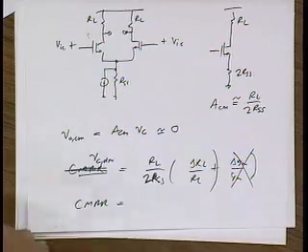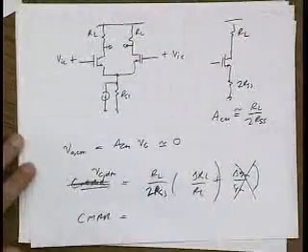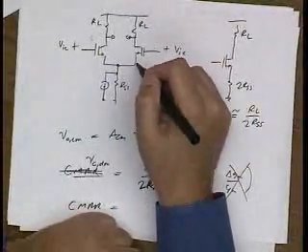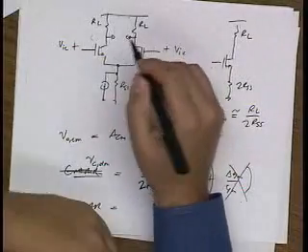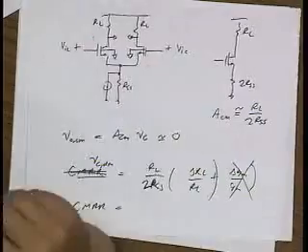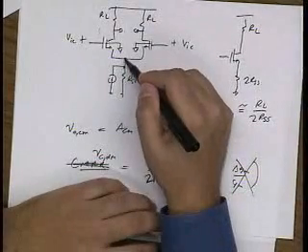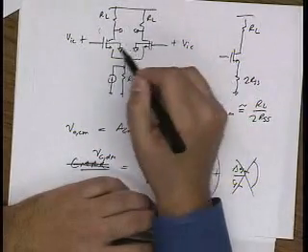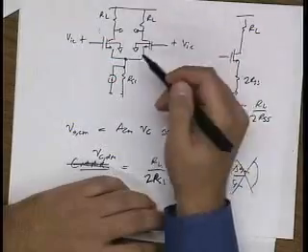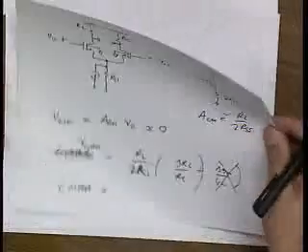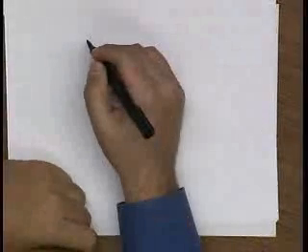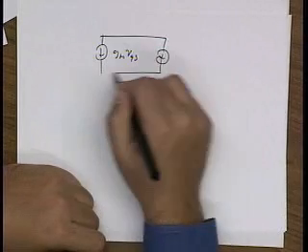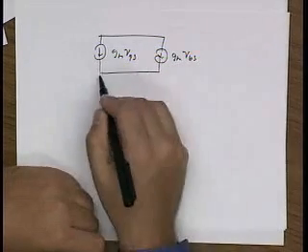Body bias. Yeah, that's right. Body effect. So ultimately, remember, for most NMOSs, the source node is connected here, but the body is grounded, right? And that means that as I vary the source voltage, I'm going to excite a voltage source to body. And if the transistors have a mismatch in their body coefficient, I'm going to get an output differential signal, right? It's that simple. So here, remember the output of a transistor is GM VGS plus GM VBS. There's a back gate.